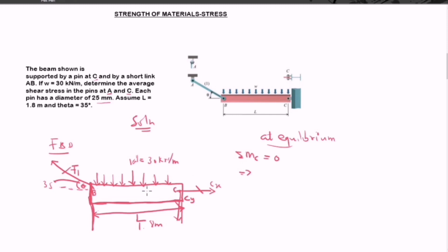Now before then, we need to resolve these forces, right? For these forces, we have a force coming here, Fy, and we have another force coming here, Fx. So we have a force that has been resolved to get F1 in the rod 1. So we are creating a moment at C. From here, this is going to move clockwise to C, and I'm taking anti-clockwise to be positive.